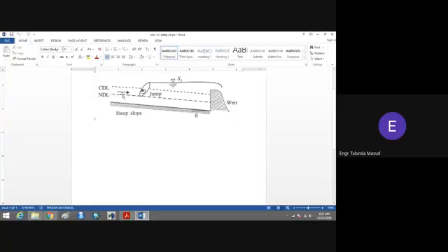The fast moving water, or you can say the flow having high velocity, is coming towards the weir, and here since it gets an obstruction or a sudden break in its velocity, there will be a hydraulic jump and the depth of the flow will be increased. So this is an important situation, that the depth of the flow will be increased.